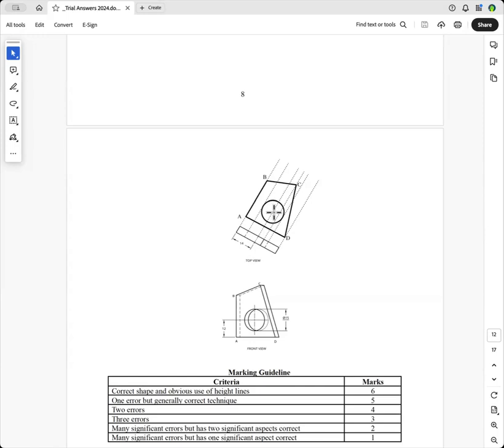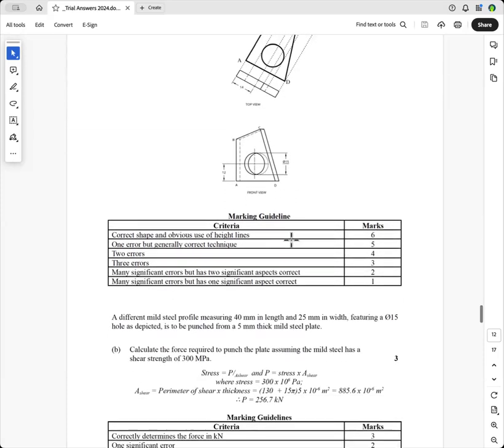Now, how do you get the diameter of the hole? Well, you know that there's a major axis of an ellipse and a minor axis of the ellipse. And when you rotate the ellipse, the minor axis doesn't change. And so therefore, that is the true length of the diameter. And so you just mark it here and there, and then just draw a circle. And so you've got the true shape of that face.